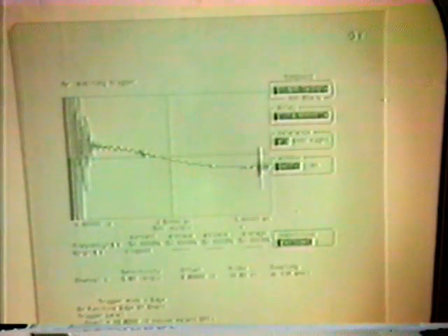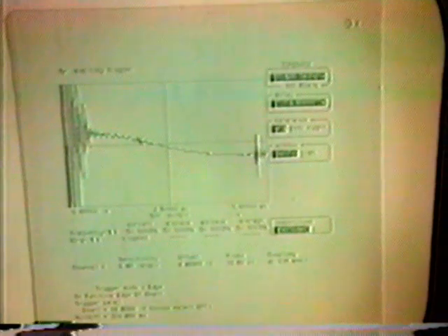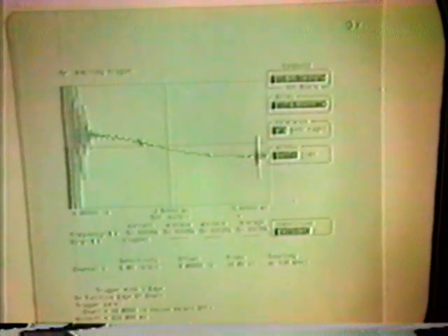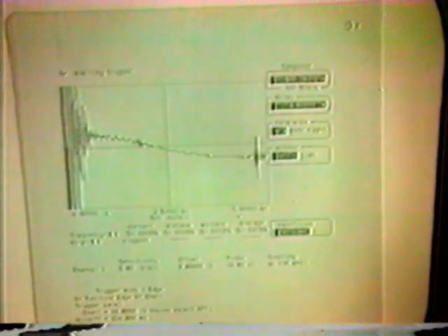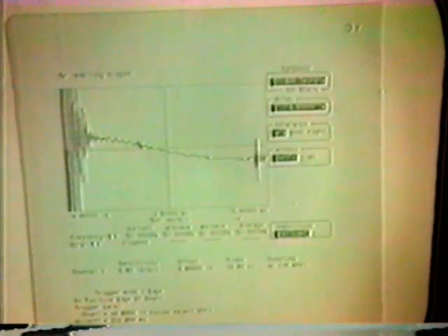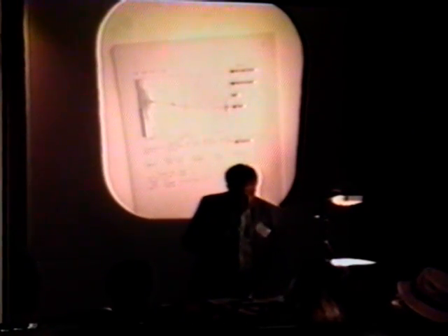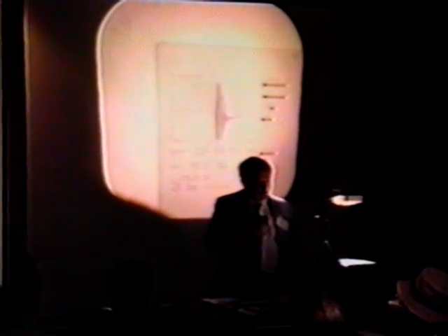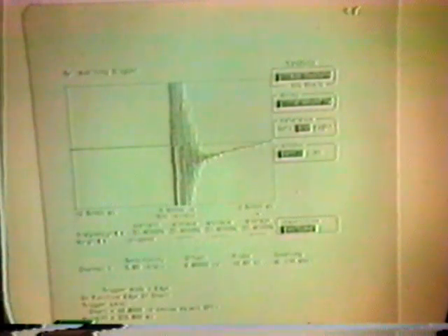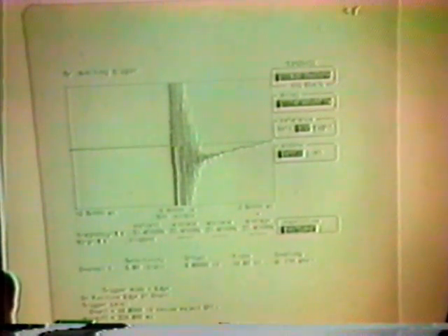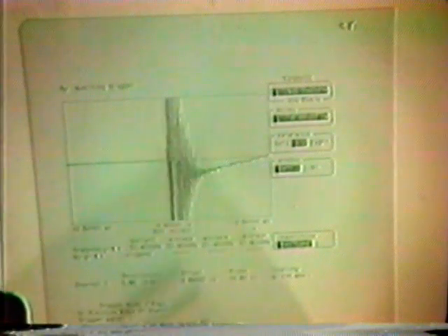Now I'll show you the same oscillogram from another setup. We have some, let's call them arc oscillations, and we see the ringing frequency present there. And an excursion again, the arc going up again. So let's look at another one. Again, the same thing. This was actually a measurement of current, by reversing the orientation of the detector coil. The oscillogram changes all polarities.